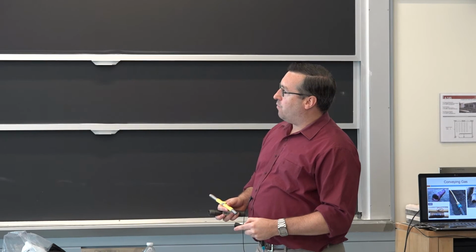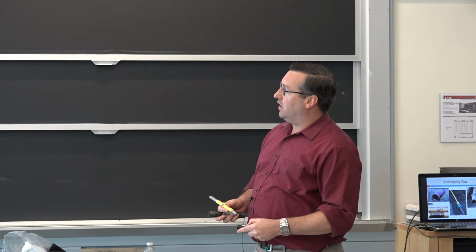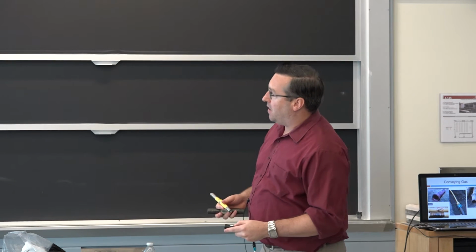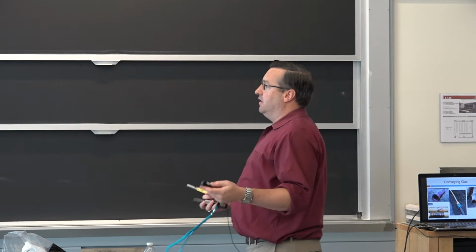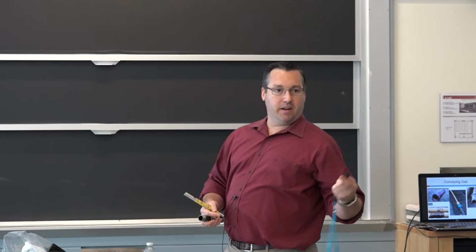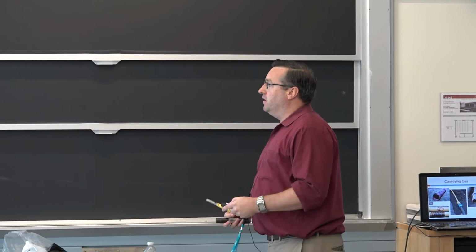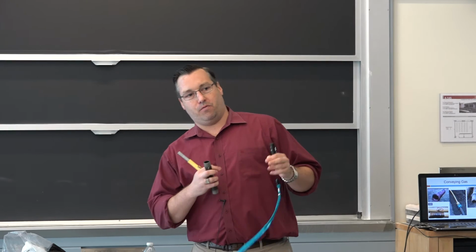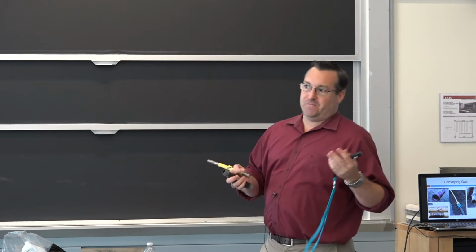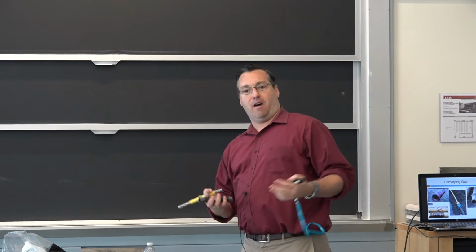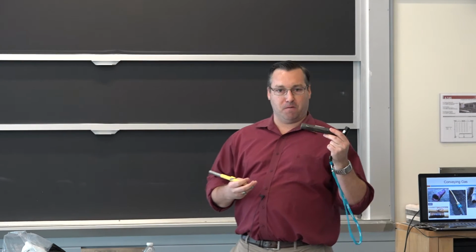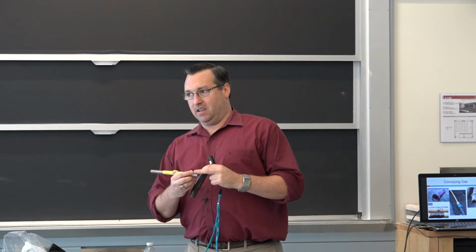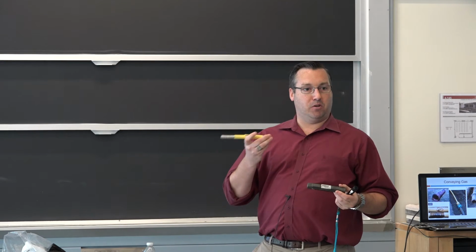So what you're seeing here is actually taken from a site where they had a puncture in this line and a fire resulted. So one of the things is when you substitute materials, you don't know, did a designer take that into account? If I'm switching from this to this, the wall thickness is going to be critical, right?